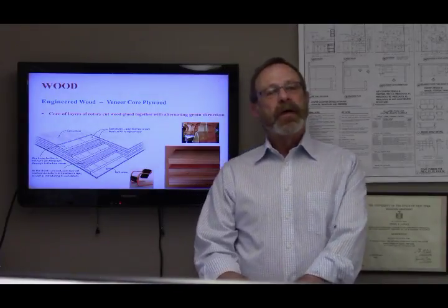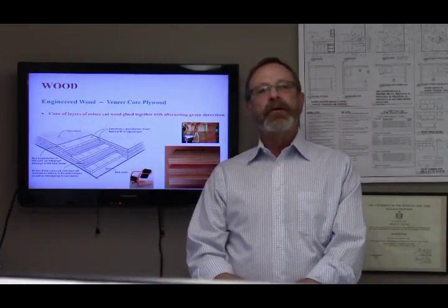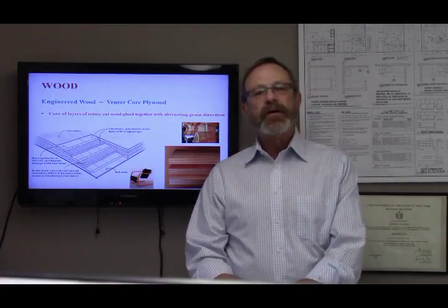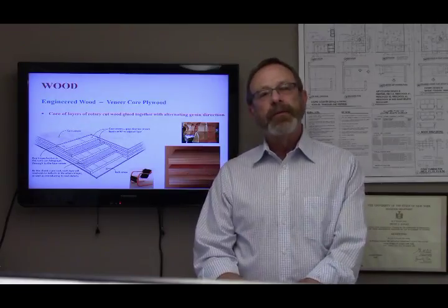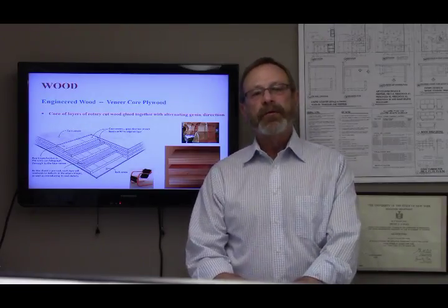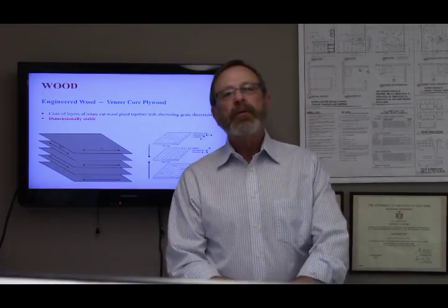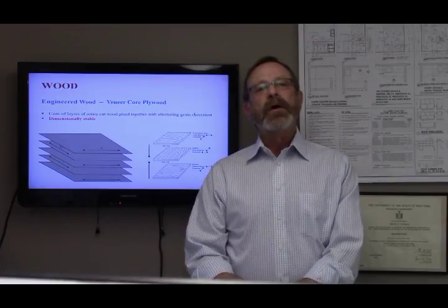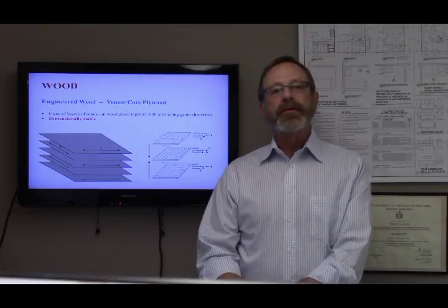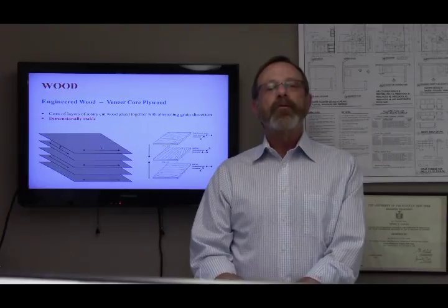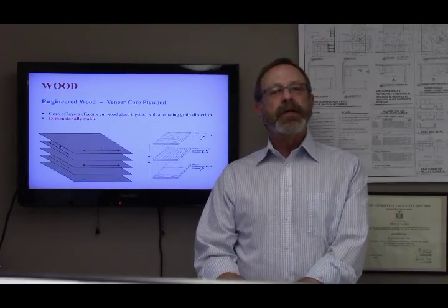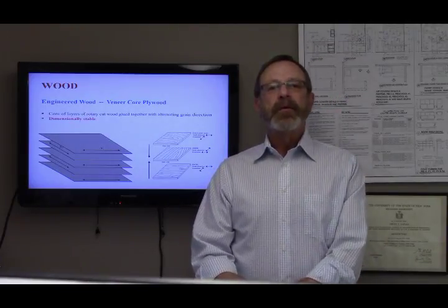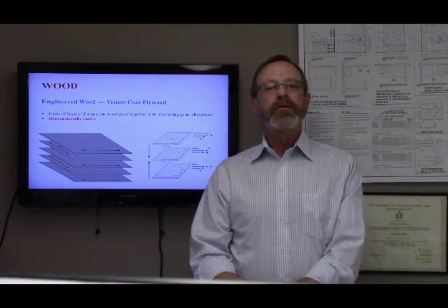Veneer core plywood has a finished wood grain surface veneer and is relatively lightweight and easy to handle. As we said, the face veneer is available in many species to suit your individual decorative need. Plywood is produced by superimposing and gluing together several layers of wood with their fibers crossed perpendicularly. This procedure, called cross-lamination, confers good rigidity, mechanical strength, and dimensional stability on the product. Plywood can be made from either softwoods or hardwoods.